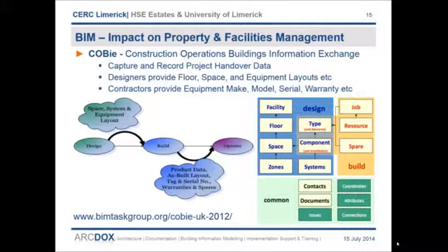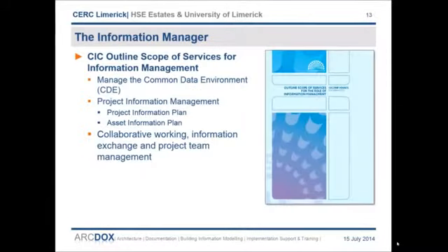As a minimum standard, COBie, Construction Operations Building Information Exchange format, has been specified in the UK using Uniclass 2 classification. This will ensure that the data is well ordered and ready to be imported into the operations systems without requiring the facilities managers to retype the information. This is set out in the specification for the digital safety file that is cross-referenced to the BIM data.